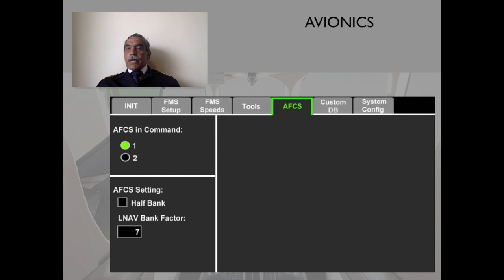That means en route, if 10 nautical miles is specified, then the system is going to adjust the radius of turn in such a way that it's not going to exceed 10 nautical miles in either direction. That's what this means.